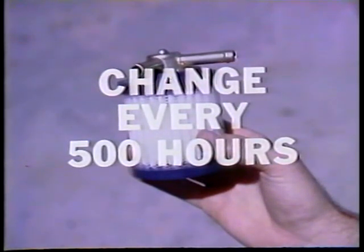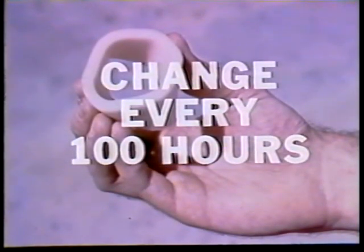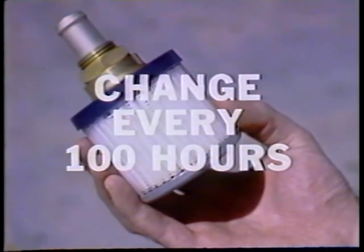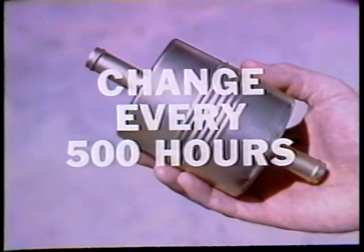In a vacuum system, replace the air filter every 500 hours or more often if the airplane is operated in extremely dusty conditions. The foam garter-type filter on the vacuum regulator should be replaced every 100 hours of operation, and again, in the event of dusty conditions, more often. In a pressure system, replace the pump inlet filter each 100 hours. The 3/10 micron inline filter, located at the inlet to the gyros, should be replaced after 500 hours.